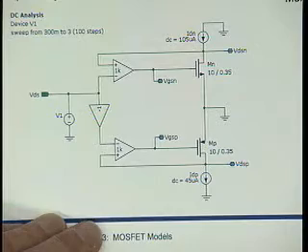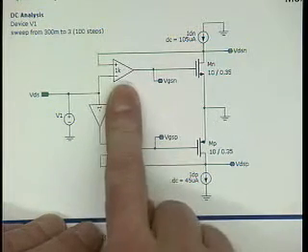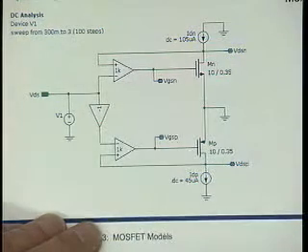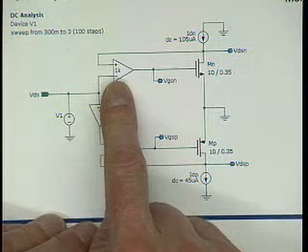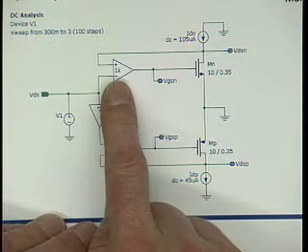And that, of course, is very easy in SPICE because amplifiers, they sort of come free, right? They have them. They're much better ones than we ever could build in an IC, for that matter. One thing, be very careful if you use an ideal amplifier in SPICE. Do not make its gain unnecessarily large. If you do so, you may have convergence problems.